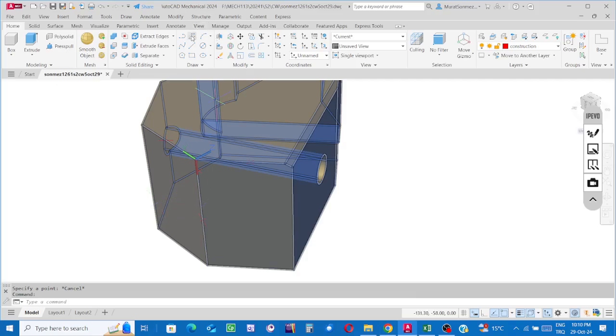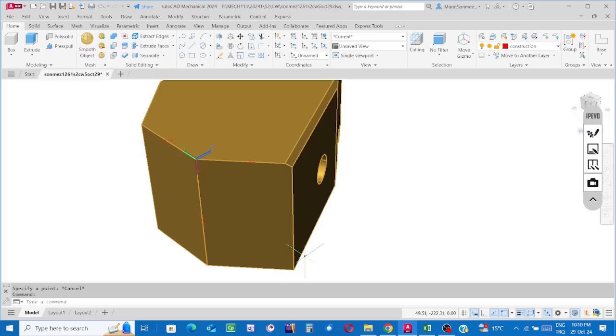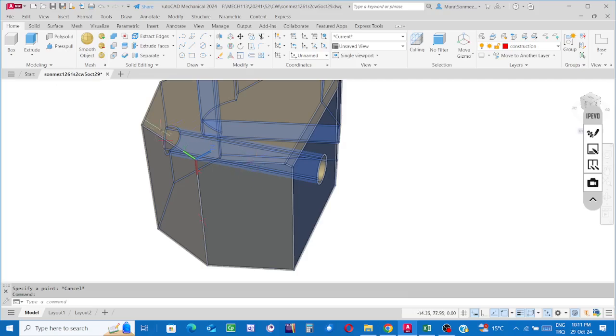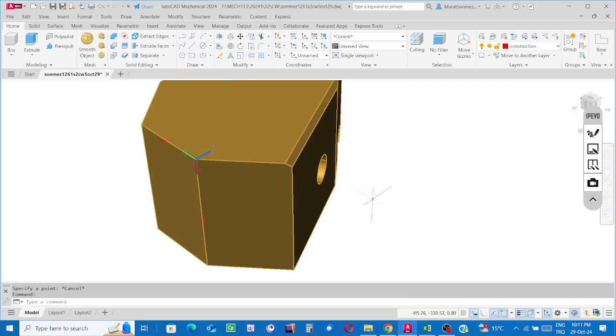So in applying the 3D polyline process, for having the boundary lines of the sketch, you can indicate 2 points but cannot indicate the third point. It's an important trick, dear students. If dynamic UCS is active, is on, then you can indicate 2 of the points but cannot indicate the third.